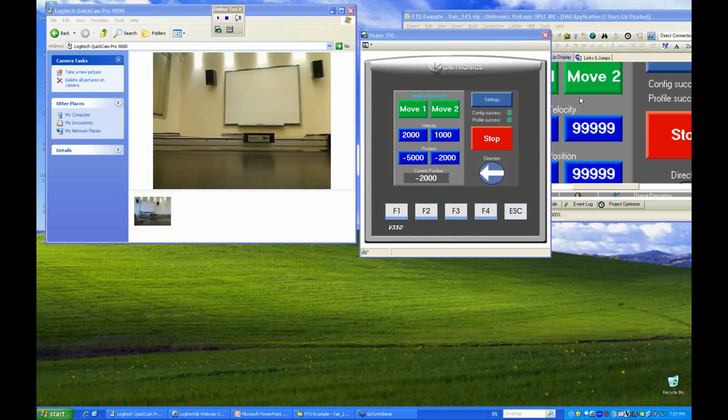There was a question why the NPN frequency is bigger than PNP. I answered this question. Once again, the PNP transistor, in fact, is a chip inside the controller. It's not a standalone transistor. It needs to switch relatively high current, up to half an ampere. This means that it has some slew rate which is relatively long, so it cannot support high frequency.